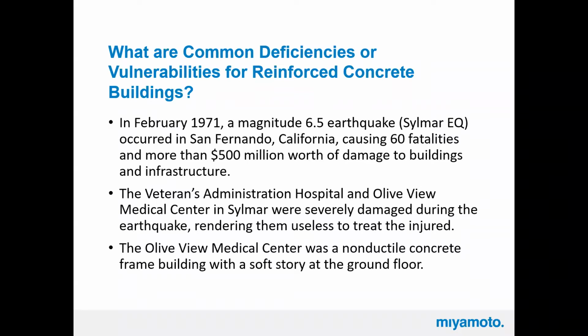Common deficiencies. Well, this just kind of goes back to all of you. For reinforced concrete, everything really goes down to non-ductility, or lack of ductility. A lot of it goes back to the older methodologies used to analyze buildings, where we didn't have the sophisticated computer software that we have now, and people were doing stuff with presumed assumptions and slide rules or even hand calculators.